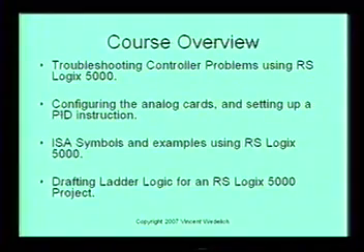Some of those items are, you're downloading the PLC, you're in remote mode or program mode, and somebody flips the switch to run mode right when you're downloading. Well, that'll create a fault. You don't want to do things like that.